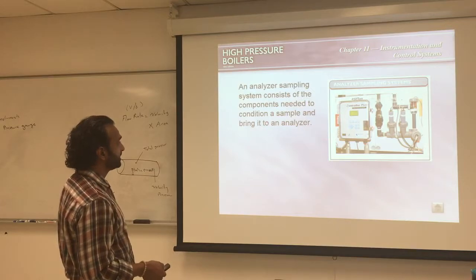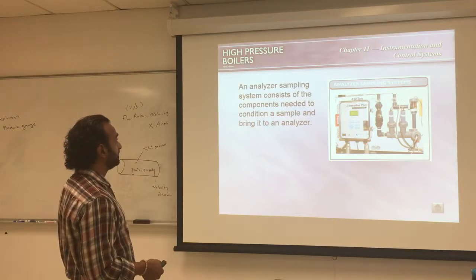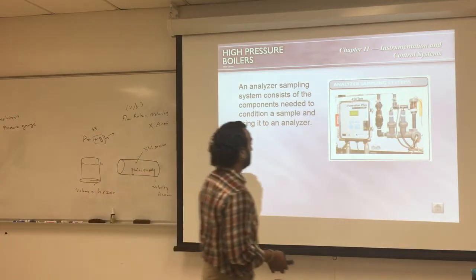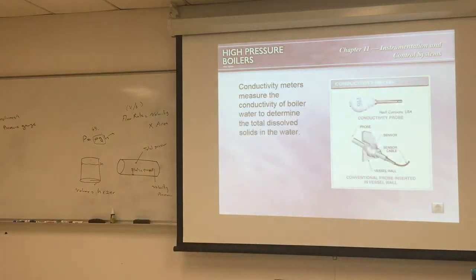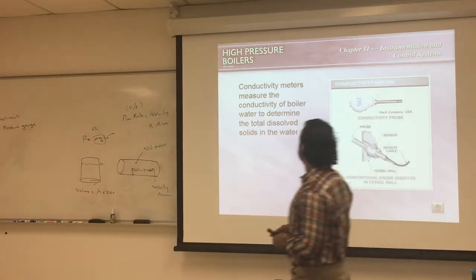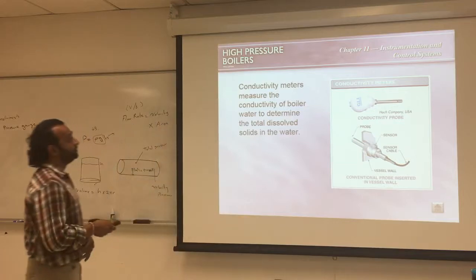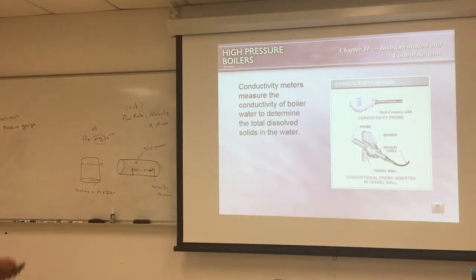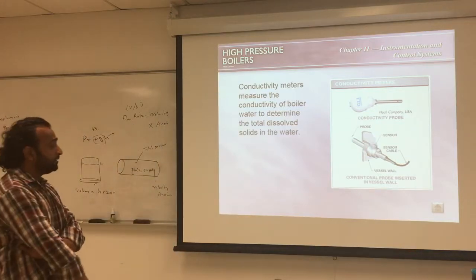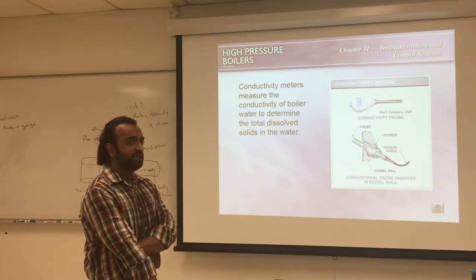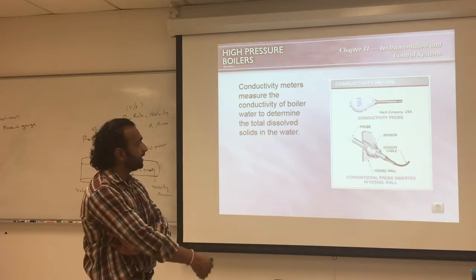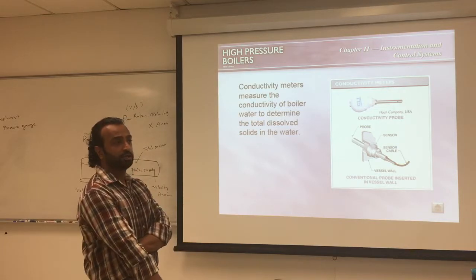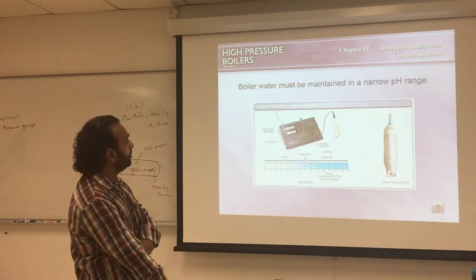This is a system analyzer that will analyze the contamination inside the feed water. Conductivity, that's a very useful instrument to use inside the tank. If you measure the conductivity of the water, what does that tell you? It tells you it has more salt. So based on the conductivity, we can know how much salt and dissolved matter is in the water.